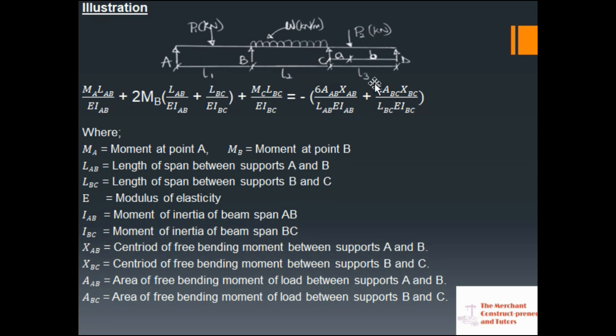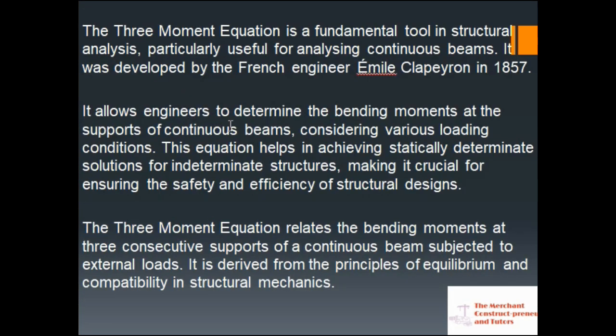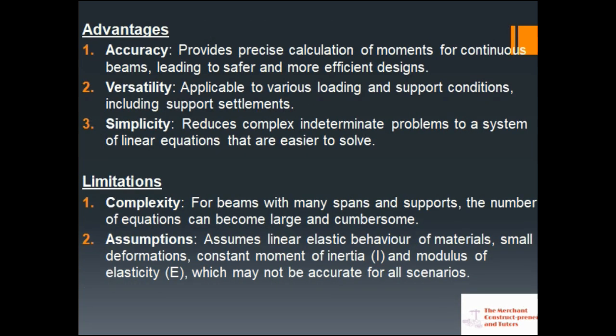Then when you are doing the second part, to include D, you take B, C, and D. If you have other supports, you continue like that, this and the next one. So I hope you understand that statement. After breaking this down, the principle of equilibrium can now be applied, since it will be broken down into statically determinate structures. So let's look at the advantages and disadvantages, or limitations.